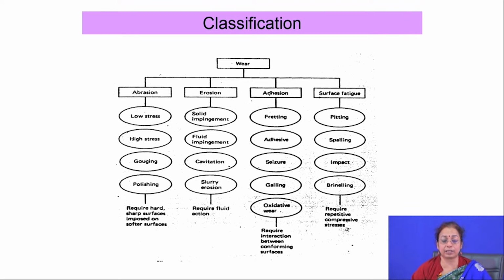For wear to occur, there has to be relative motion between two surfaces, and wear is actually measured in terms of the loss of material. Most wear involves loss of material from the surface, except in a few cases, but there are different ways by which wear occurs, depending on the kind of meeting surface the component is facing, the hardness differences between the surfaces, and the environment the component is facing.